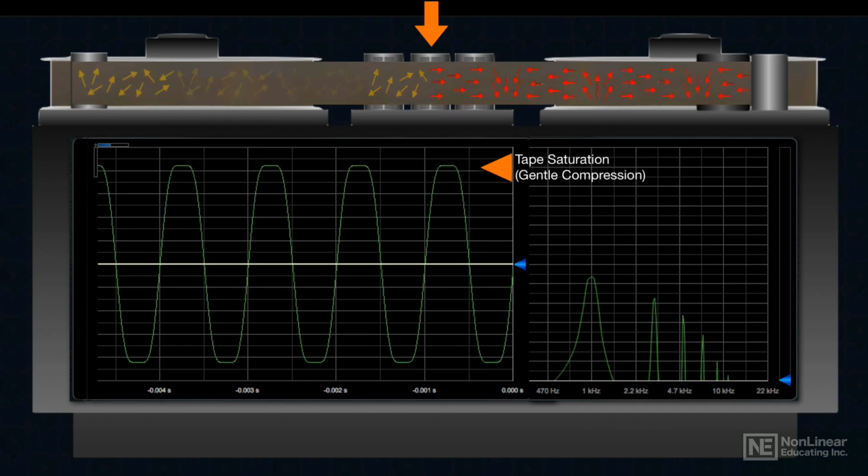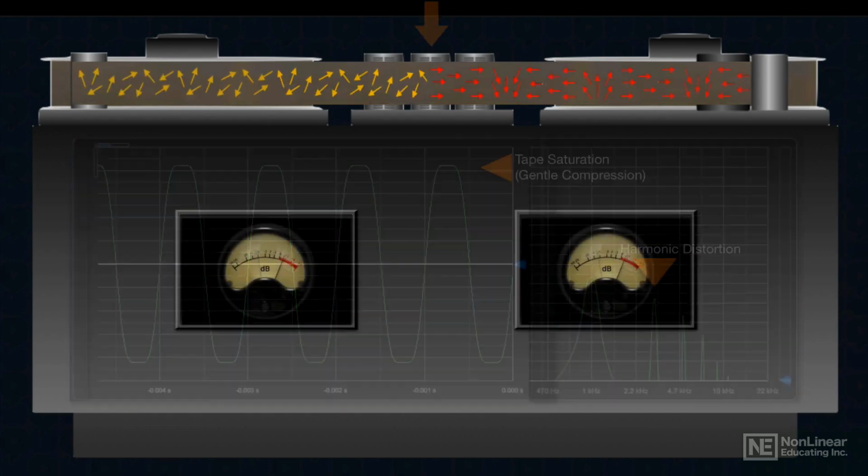Higher incoming signal levels will not be reflected in the recording signal, gently clipping or distorting it at higher audio levels. Excess tape saturation is technically a flaw, but in small amounts it can add a little analog warmth and presence to the signal, and this effect, if managed carefully, is a part of the appealing sound of analog tape.